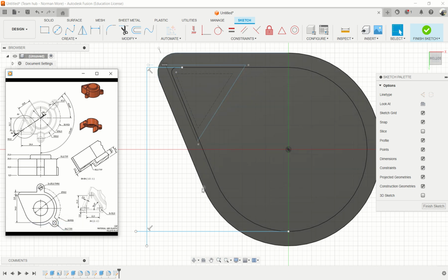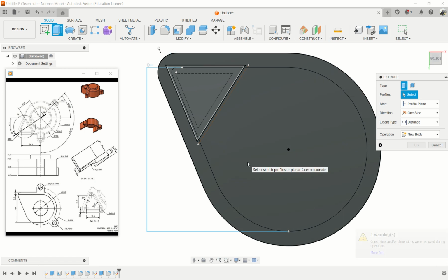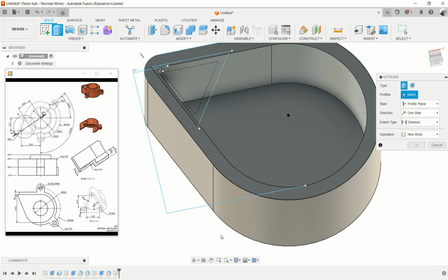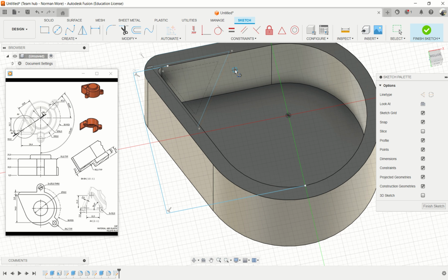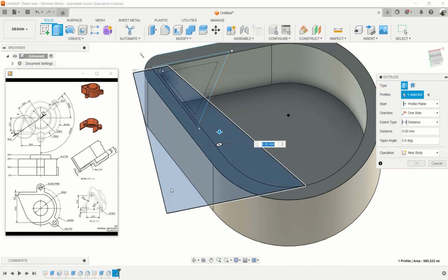So after that, I can trim off these ends in. Not quite necessary. And then I'm going to extrude cut this so that I leave 3 mils at the bottom. So since it is 20, I'm going to do extrude cut, and the distance. Okay, it's not a full one, do a line and make sure that the whole thing is closed, and then I do extrude cut, and I just put in -17.